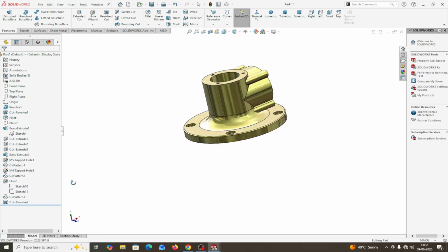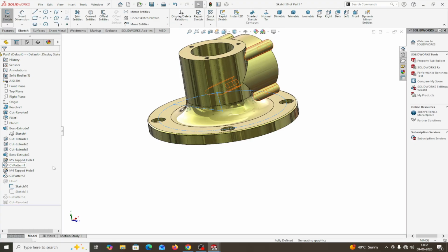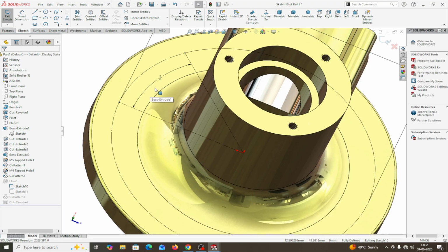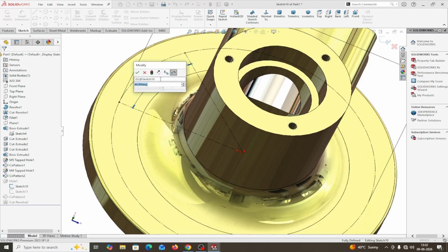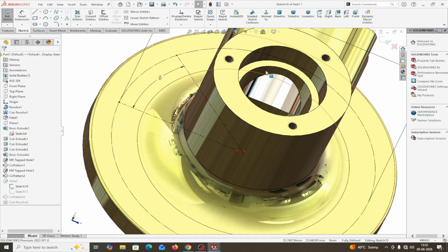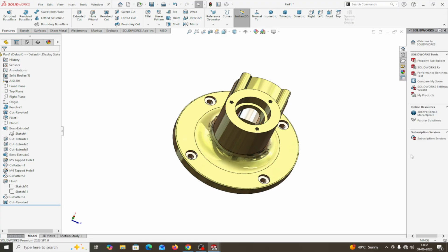Or you can leave it, you can change it, otherwise you can change from here also. Actually this is 40 degree. And hit right button. This one, hit button. So angle between 3 holes is 40 degree.